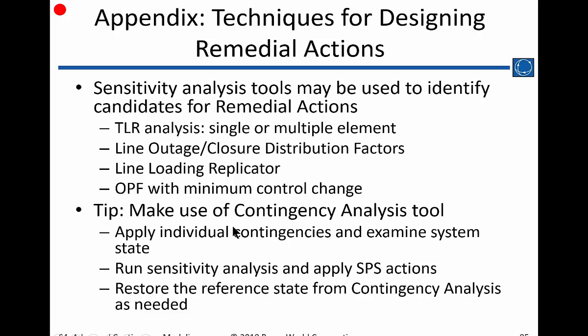But if you're in a position to have to design these, like operations planning engineers might have to, this goes through the use of some of our sensitivity analysis tools like TLR or line outage distribution factors, our line loading replicator, our optimal power flow with a minimum control change objective function, and how you can use those to identify controls that work.